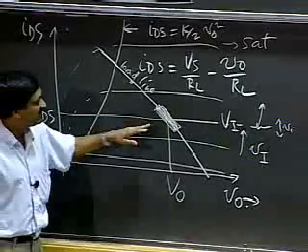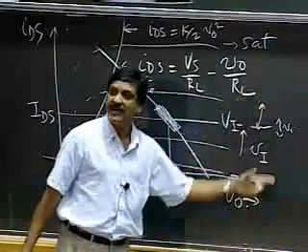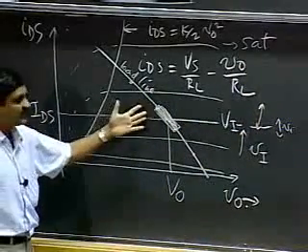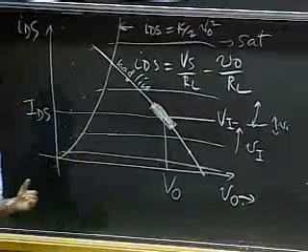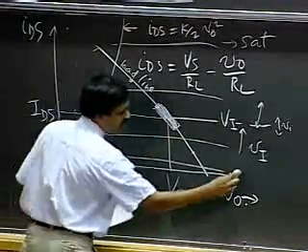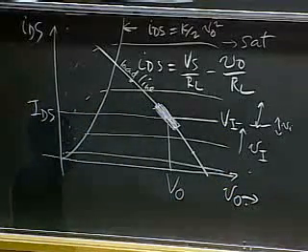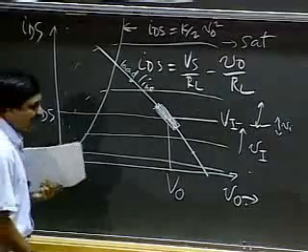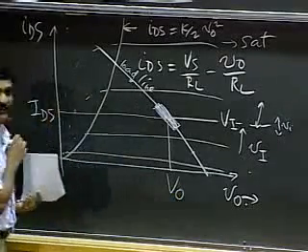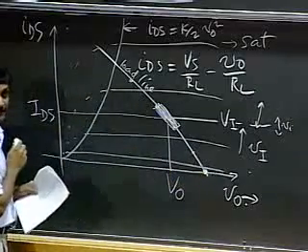Notice now the operating range: how far can VI vary before the MOSFET goes out of its saturation discipline? Well, on the low side, my VI can come down to here, and we looked at the operating ranges for an amplifier, and I can come all the way down to VT. At that point, the output will come here.